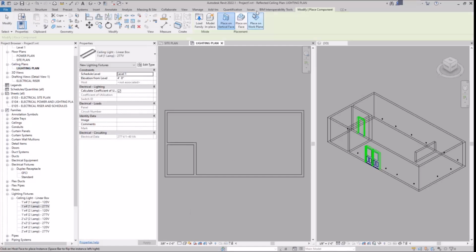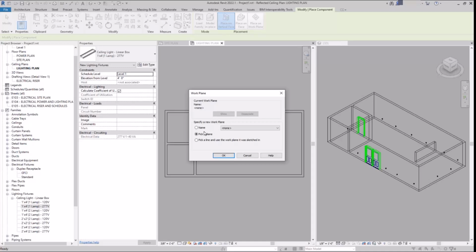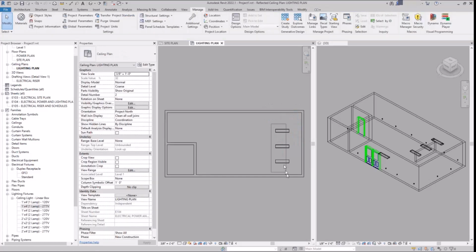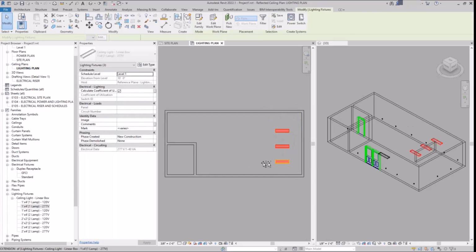The reason for that is because our client has a 480 volt generator. He wants to be able to connect this 480 volt generator to this building without having to have a whole lot of stuff. We won't show the generator connection, but the idea is he's got a 480 volt generator. He wants to be able to plug right into this. And since 277 lights are much more efficient than 120, that's why we're doing 277 volt.